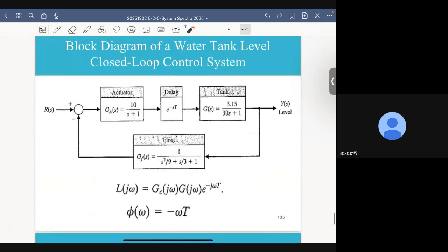Now remember, this diagram tells you one thing that we always have to remember: the actuator as well as our sensor are subsystems. They always have their own dynamics, because when the water surface increases or decreases, the flow will fluctuate a while before it settles down.